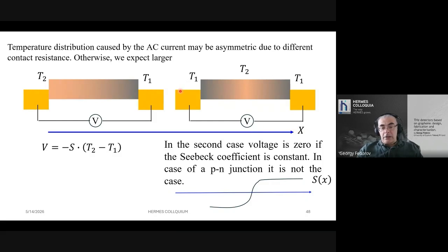On the right side, I show that the Joule heating results in temperature elevated in the middle, because if the contact resistance is the same, you would have a bigger temperature in the middle because heat goes away to the contacts since they are metallic. And in the middle, which is far from either of these contacts, the temperature will be larger.